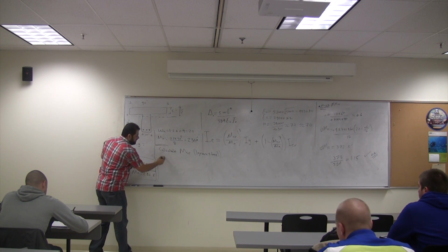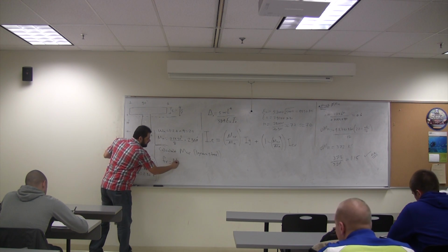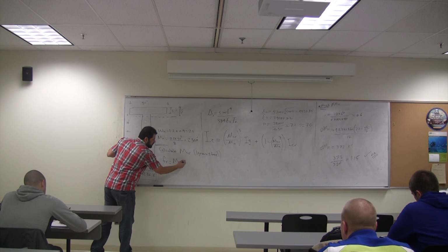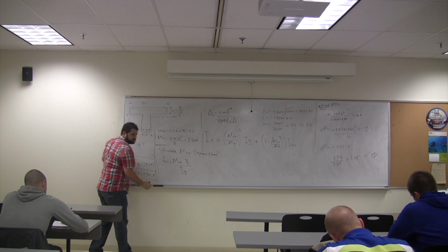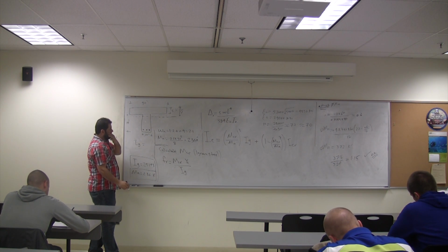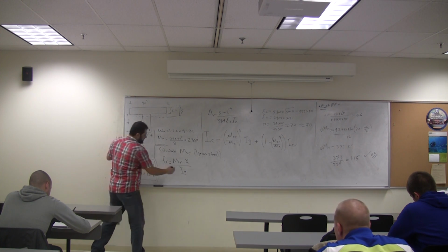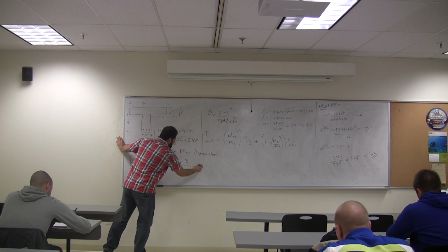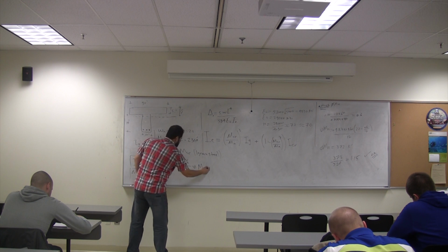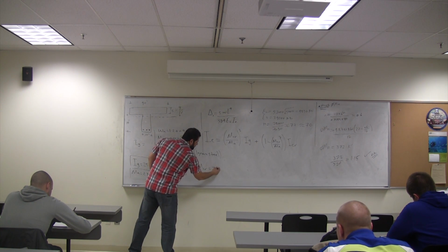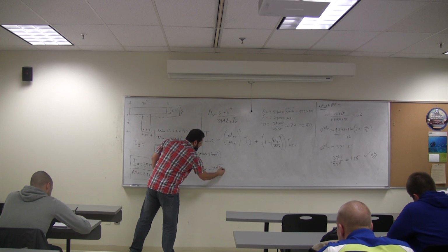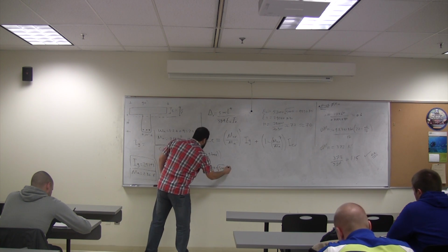So look, FR equals M crack Y to the tension over I gross. Okay, over I gross. So M crack equals FR times I gross over Y tension. What's FR? 7.45 square root of F prime C. What's I gross?